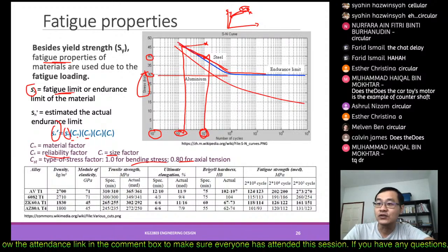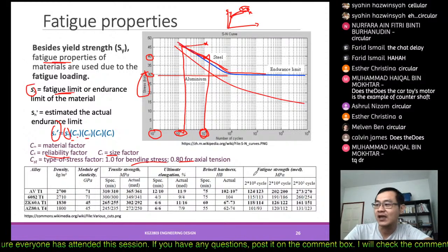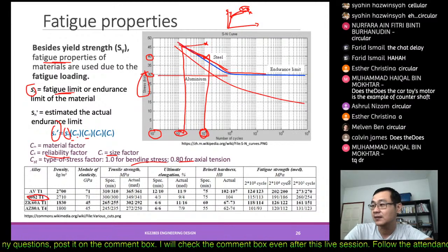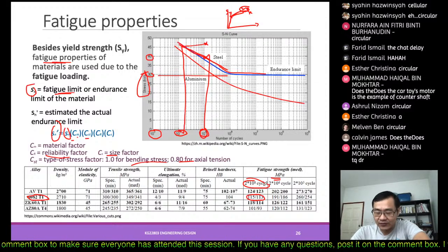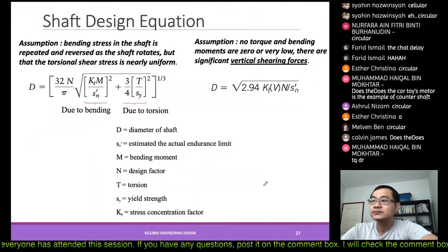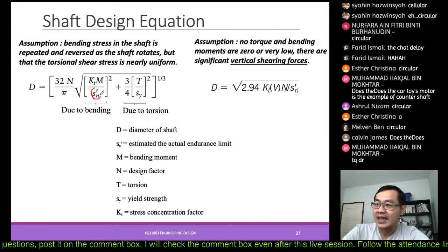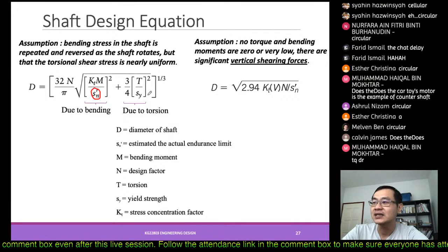If we want to get this value, we can always refer to the internet or some design book where they have material properties, for example, or in papers. The material will be able to sustain a number of megapascals, around this value, under this kind of number of cycles. Now how would we use that? We would use that estimated fatigue limit in our design.